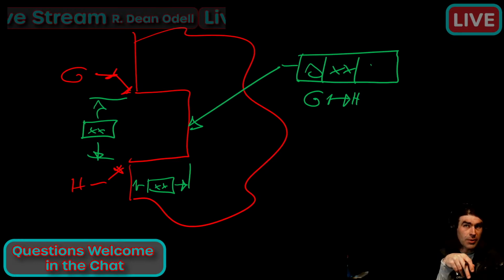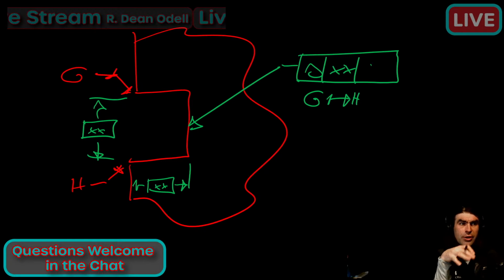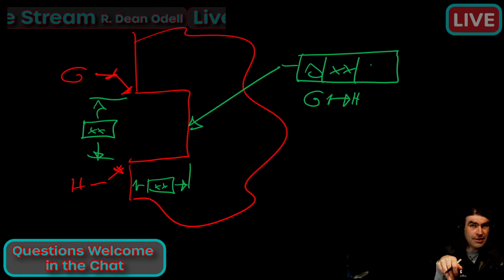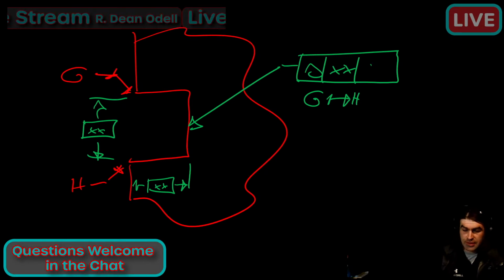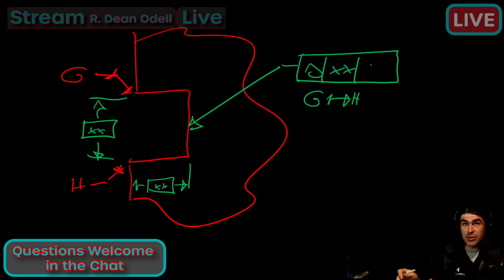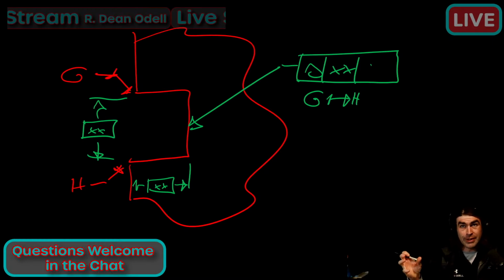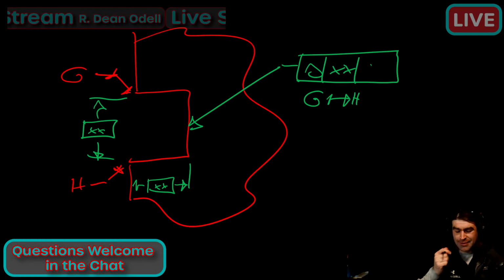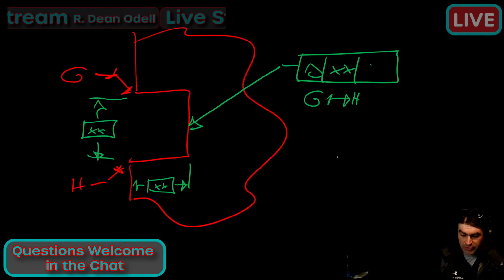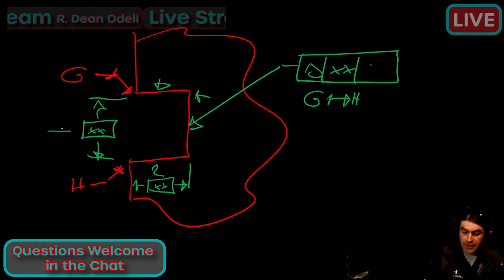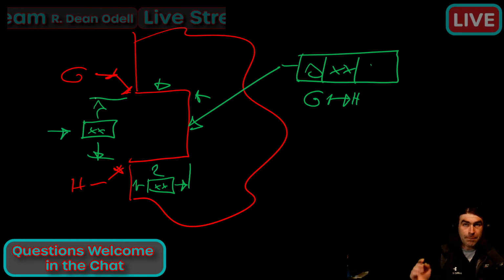There are some situations where you could use profile, like parallelism. In this case, it wouldn't work, because we're controlling essentially a feature of size. I'm not sure if I would want to encourage thinking about it that way, but it's a collection of three surfaces. This is a feature of size.